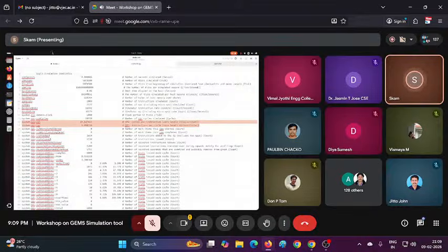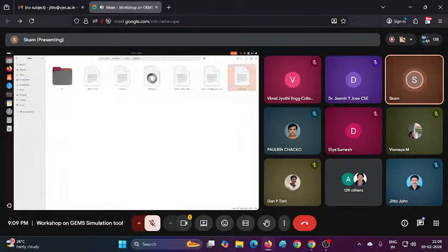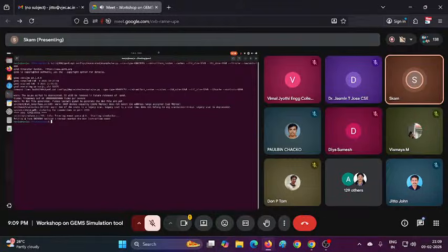So one such parameter is CPI or IPC, and you can see the value here. What you can do is have a base model where you won't make any changes. You note down the CPI and IPC, and after that, whatever you want to integrate into gem5, you integrate. Then you run and check the CPI and IPC values. If the IPC value is going high and CPI is going low, you can evaluate that as a good model. This is one way you will be assessing your processor.